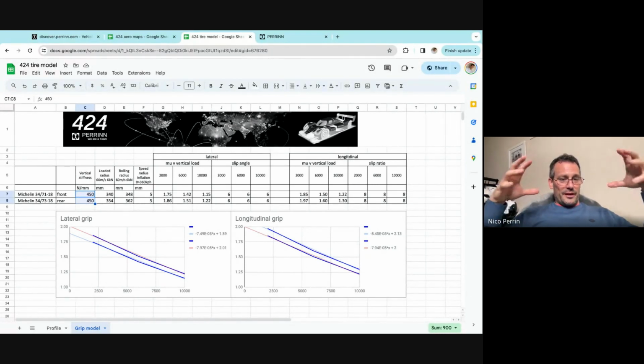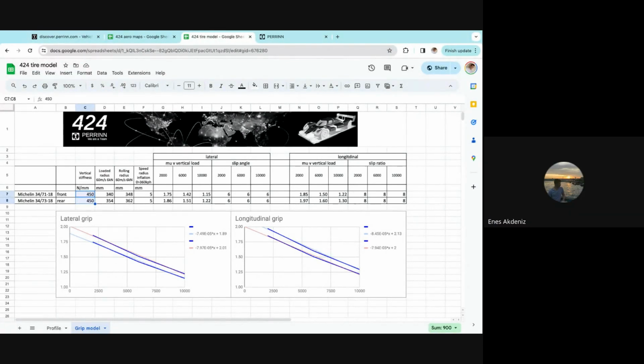And typically the tire manufacturer, the first thing they will want to know is what will be the maximum load that the tire will have to take, and the maximum speed as well. That will define the sort of carcass that they will have to use, just purely from a reliability point of view. Okay, we don't want the tire to explode. That's the first thing.